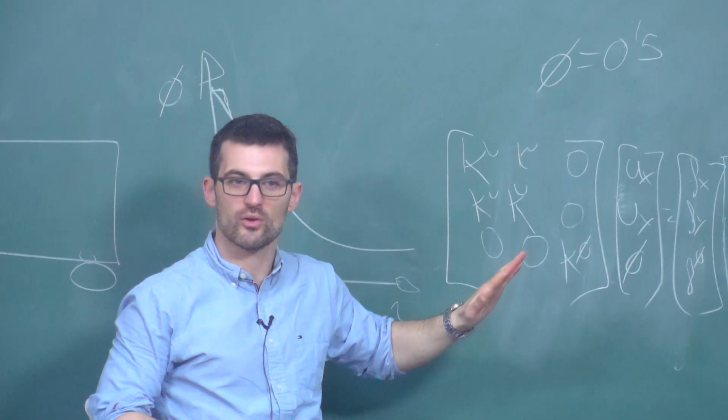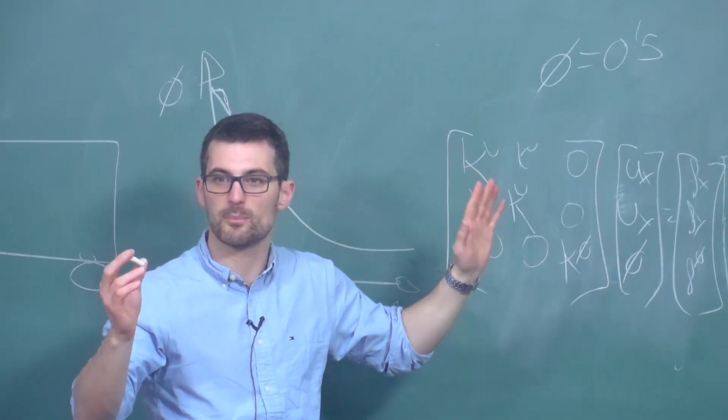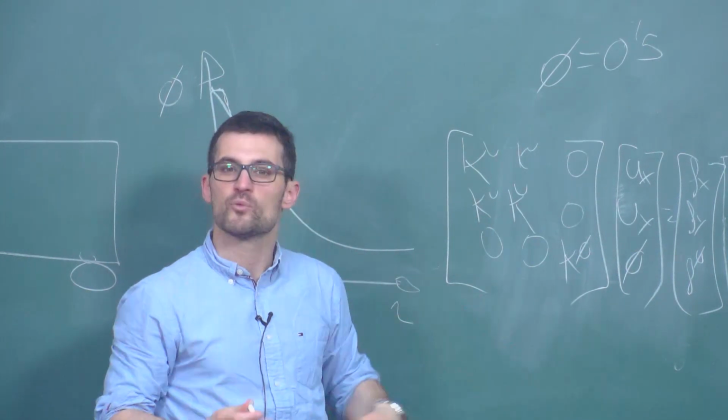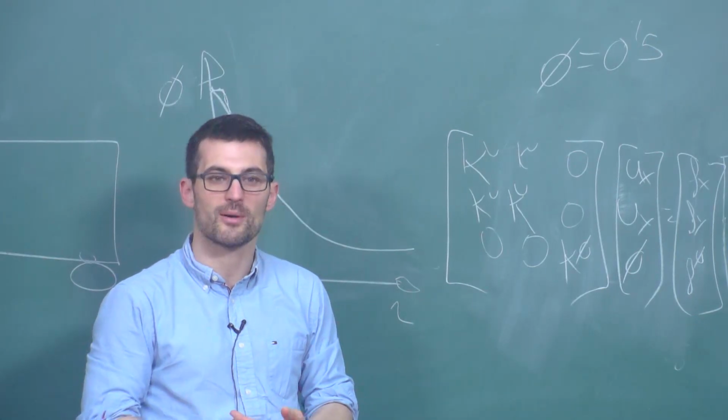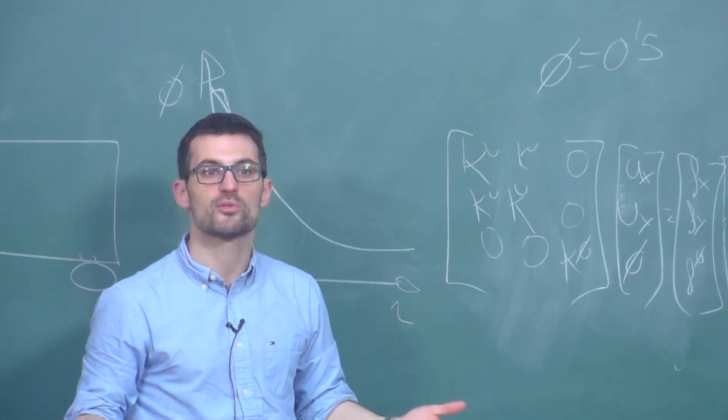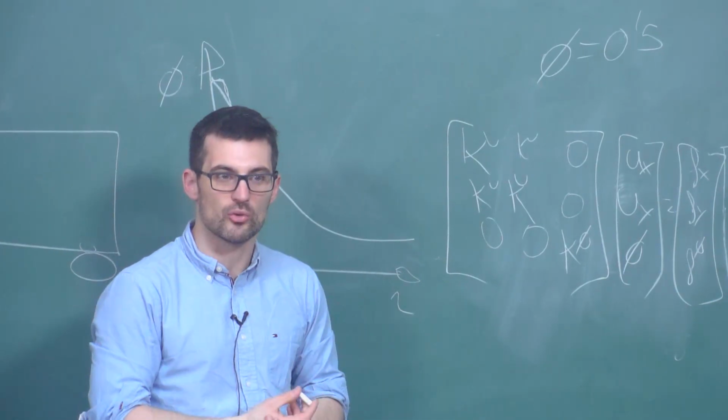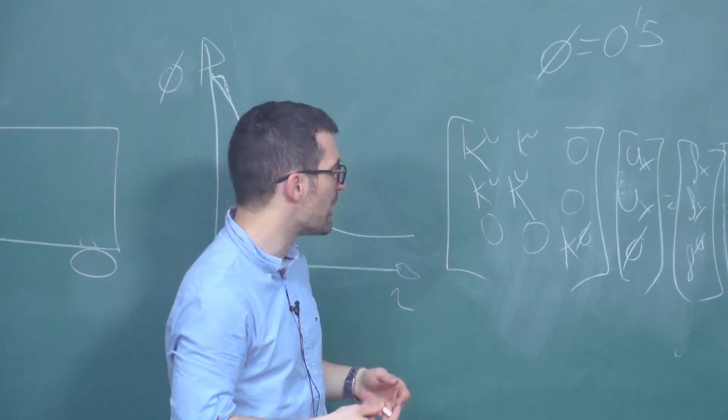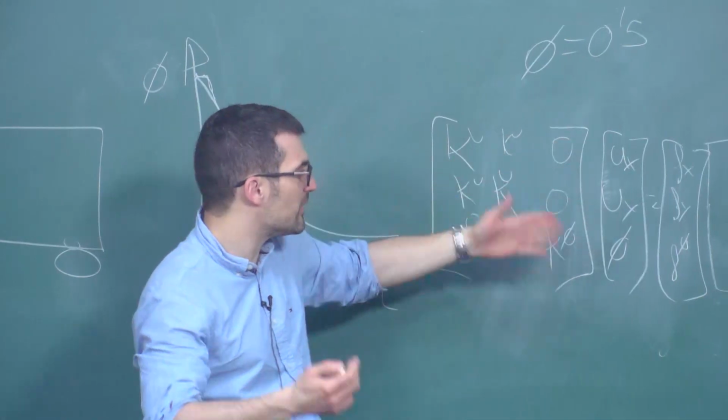It doesn't know anything, whether you're using a Lagrangian element or a serendipity element. So a lot of, for example, the contact options of Abaqus do not work. The visualization options of Abaqus do not work. You need to do some tricks to visualize things. You use typically a dummy mesh. So it's a bit messy, but I mean, this is what we thought we had to do, right?